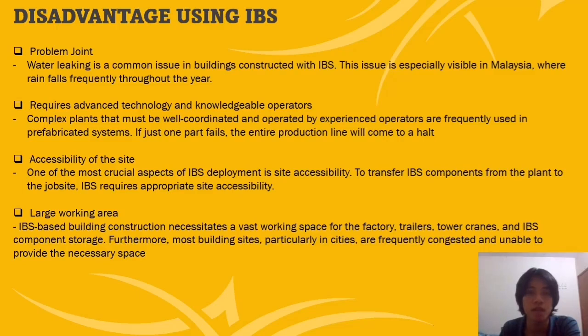And the last one is large working area. IBS-based building construction necessitates a vast working space for the factory, trailer, tower crane, and IBS component storage. Furthermore, most building sites, particularly in cities, are frequently congested and unable to provide the necessary space.